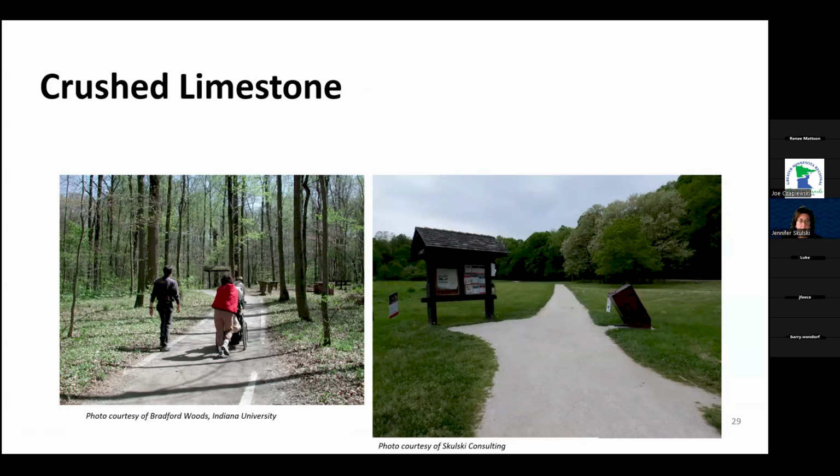It's a mix of stone, 50% stone, where the stone size is a 1/4 inch or smaller, mixed with 50% dust, and then installed, wetted, and compacted and wetted. And then over time, it will set up just as hard as concrete. It's a really nice trail surface. There's a lot of use of it in the Midwest with the National Park Service.